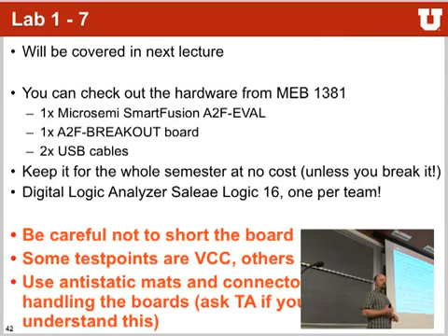Be careful not to short the board. Some of these small little pins that are coming up, some of them are power, the other ones are ground. Don't hook them up together. Don't put your leads on both of them, or bad things happen and they break. Use anti-static mats in the lab. The lab has anti-static mats, so if you are in the lab downstairs, first of all, always quickly touch the ground so you're not electrostatically charged, and then use one of these mats to work on. Also put the hardware back into the little anti-static bags that they're coming in. It really helps keep the hardware from getting fried and broken. I do understand, stuff happens, stuff breaks, that's expected, but just try to be careful.